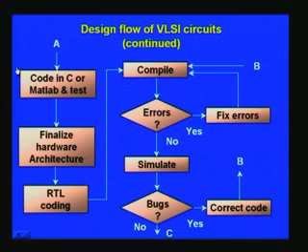And in order to prove that, you need to go for a higher level language such as C or MATLAB, and then code it in one of these or both if you wish, and finally test it with all possible combinations and IO combinations that you may be encountering later on in the actual design when you implement the hardware as such. So once this is through and you are sure that your concept is working, and you can even get user feedback even at this stage, although it's not shown, then it is ripe time for you to start the hardware design as such.